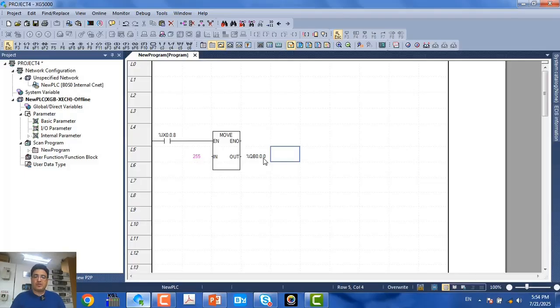And that's exactly what we wanted, meaning the first byte or the first 8 bits of our outputs, that is Q0 to Q7, are set to 1. When this function of ours is enabled, that is, when we set input number 8 of the PLC to 1, this function gets enabled and this value is set inside our PLC.